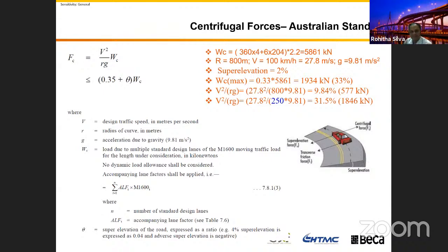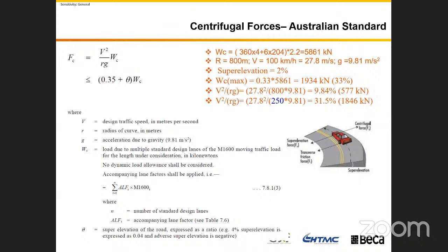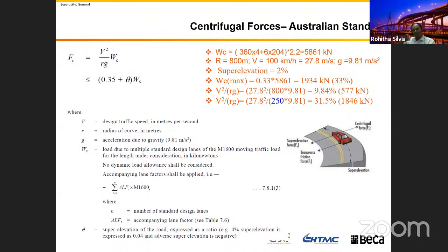Did I answer your question? Yeah, okay. Thank you, Mr. Rohit. You mentioned L over 360, because normally we design bridges for close to L over 800 in AASHTO. In the Australian standard it is L over 600, but when we design it is close to more than L over 800 for live load deflection. But for differential settlement, if you get a sag on the bridge of more than L over 360, I think there's a relationship.